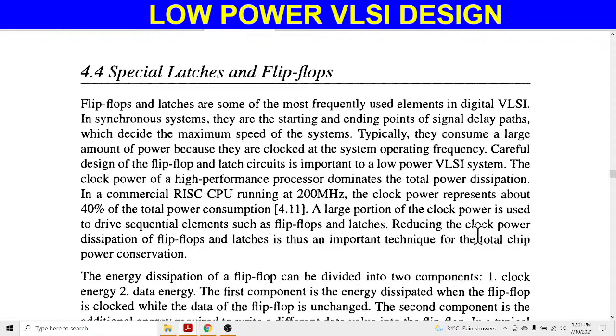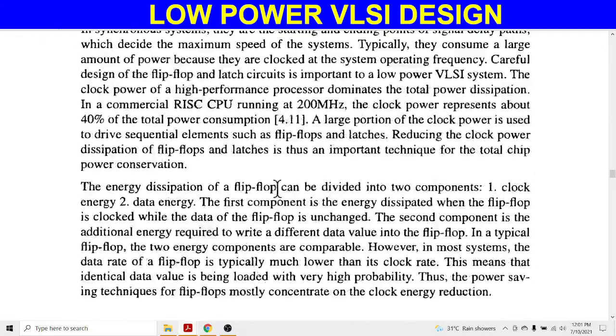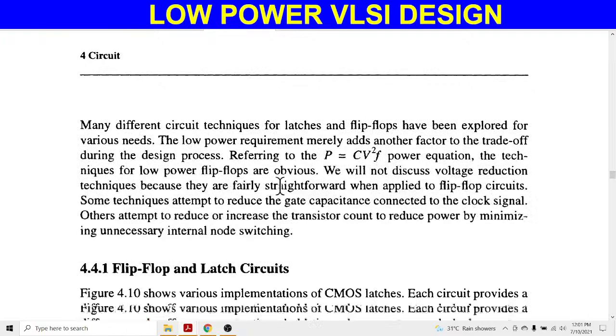Okay, this is power dissipated from any device, not flip-flop. So this power dissipation needs to be minimized. To minimize this, we know that the power is divided into these factors: capacitance, voltage, that is swing voltage, or we can say supply voltage, and the last one, which is most important, is frequency.